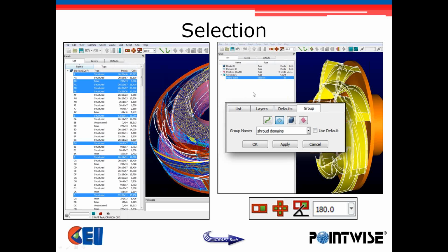Groups help you organize things, but they're more for selection. You can create a group for the different entity types in Pointwise: database entities, connectors, domains, and blocks. As the example shows in the back, I've created a group for the impeller blades, so when I select that group, all the impeller blades are selected. I could then modify their display attributes, change their color, or apply a surface mesh to them.